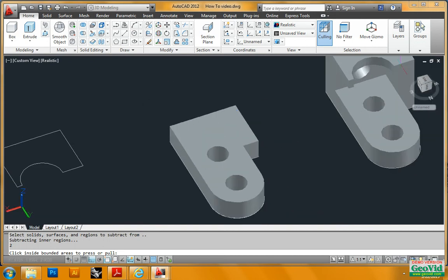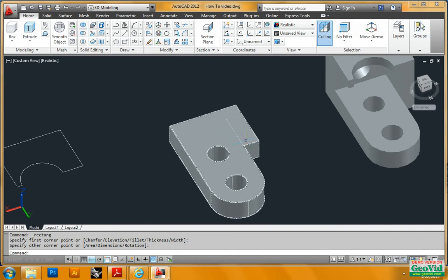So the next step is I'm going to build this side part over here. To do that, I'm just going to draw a quick rectangle right here, and off the paper you can see that it'll be 4 units high. So I'm going to push pull this square, so I just hit the push pull, and you can see now it cut into 2 separate objects.